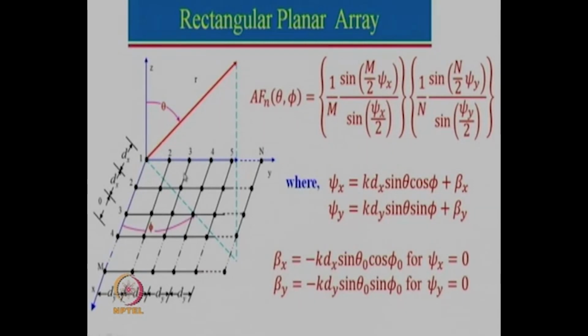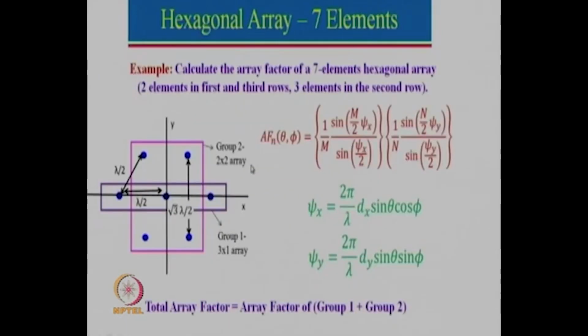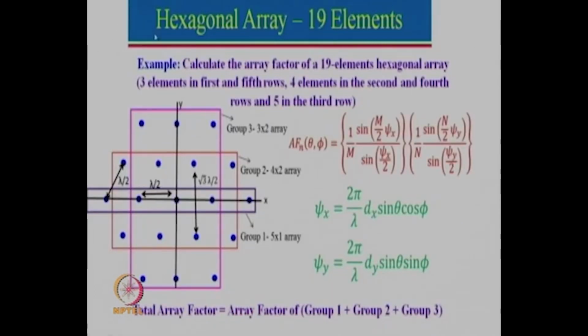That is where a hexagonal array does help. If you look at a hexagonal array which we just looked at, over here this distance is lambda by 2, or if I take this as d, then this is d. So I can still take this as 0.7 and this also as 0.7, and I do not have that problem at 45 degrees. So many times hexagonal arrays are preferred, and as I mentioned, I had designed this particular array way back in 85, and I did use a microstrip antenna.